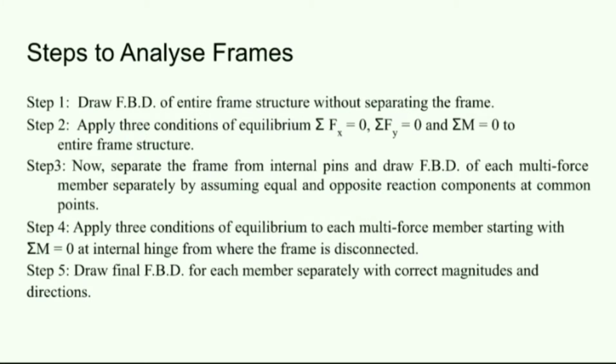Next we'll see the steps to analyze the frame. First step, draw the FBD of the entire frame structure without separating the frame. Step number 2, apply all three conditions of equilibrium, that is summation Fx = 0, summation Fy = 0, summation of moment = 0 to the entire frame structure, and calculate the magnitudes of the support reactions.